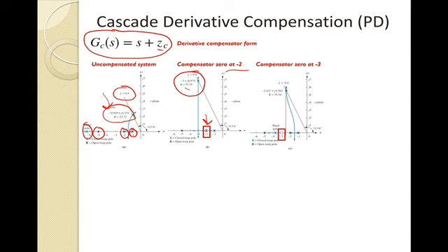We achieved the same damping. We're still on that 0.4 damping line, but notice that the poles will move accordingly from that cancellation with the pole at s = -2. Then we can look at a compensator if we move the zero to -3 as shown here. We can also, again, vary K to get on the same damping line as shown there. K would come down between those two cases.